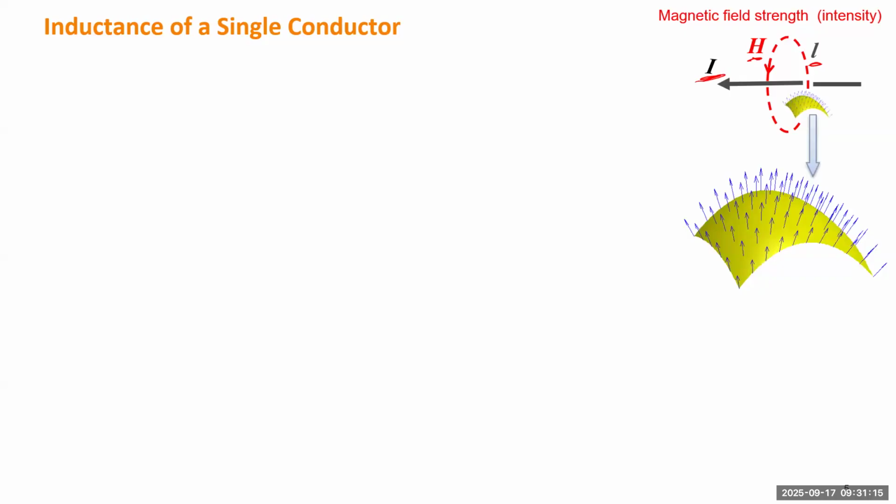If we are able to count the density of flux along that circular path for a very small area, you will see that there's a flux direction pointing to the north in that local area. If you can measure the density of the magnetic flux, you can count the flux divided by that area, and that will give you B. B is called the magnetic flux density. So H and B are different things.